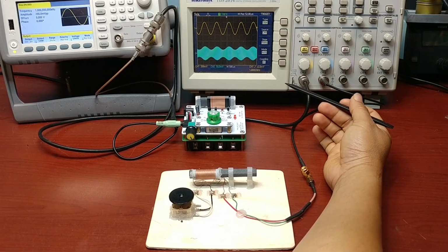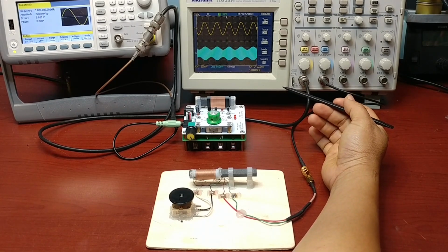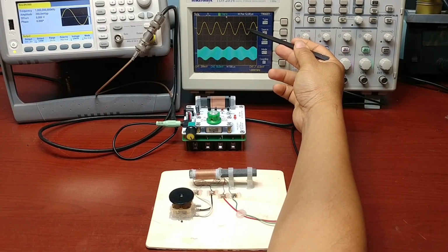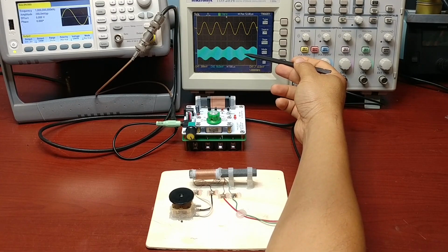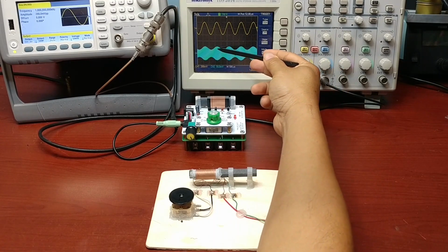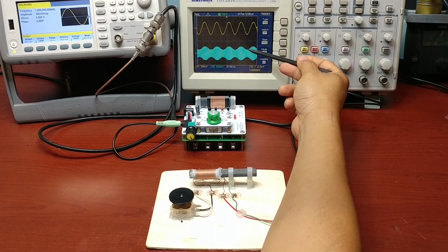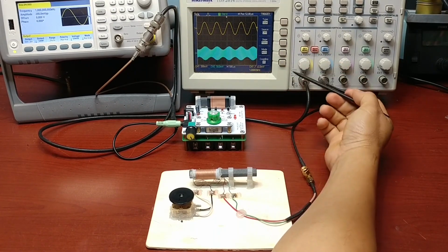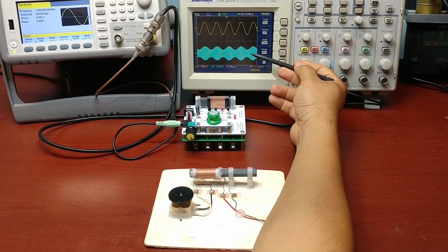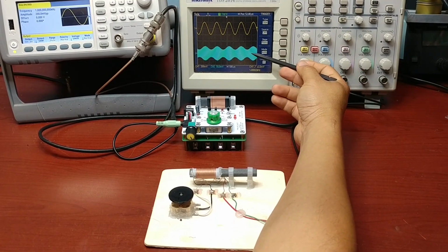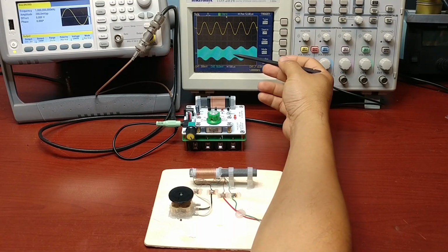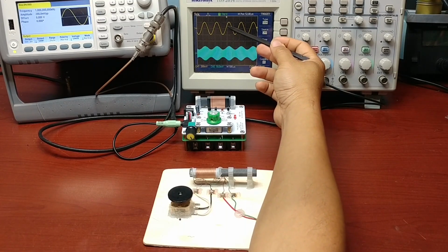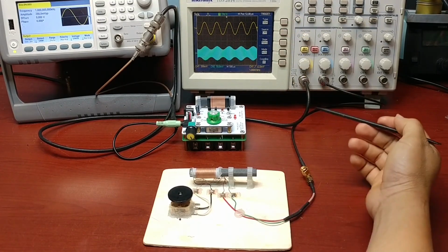As you may know, AM is the abbreviation for amplitude modulation. This input signal modulates the amplitude of the carrier frequency, making the envelope of the carrier frequency have the shape of the input signal. If the input modulating signal is a voice signal, we will see the envelope of the carrier frequency changing as the voice signal. And this signal is the amplitude modulated signal, as we can see the amplitude of the carrier frequency changing up and down like the input signal.